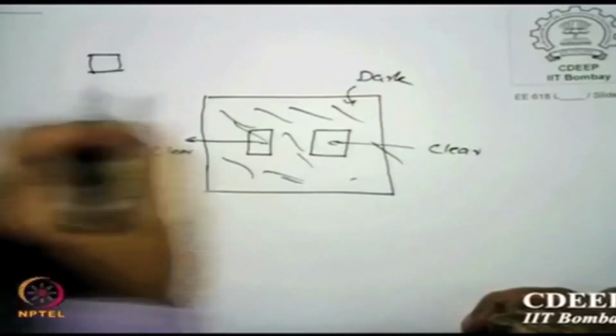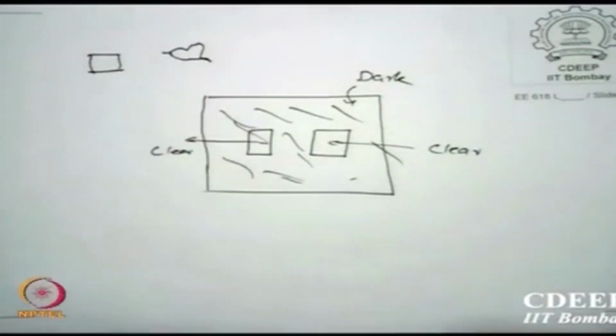The other problem which technology people are now getting, because of 20 nanometers, 30 nanometers or less, is that features are so small that when I actually do whatever etching, the pattern which I see has nothing to do with the pattern which was on the mask. So for example, I may have this actually, but what I may get is something like this. Now how do I get that area which I was looking for? Okay.